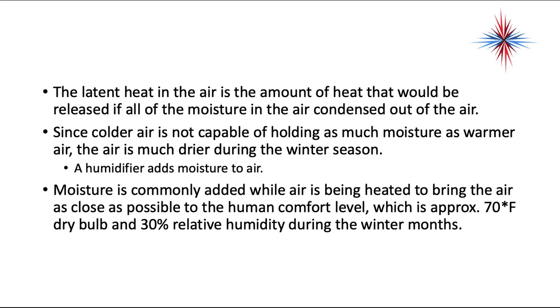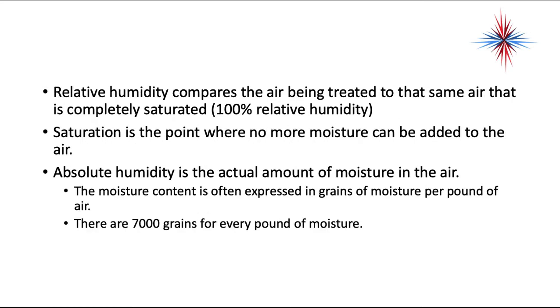Remember, at any temperature, the more humidity in the air, the warmer you feel. The less humidity in the air, the cooler you feel. Relative humidity compares the air that is being treated to the same air that is completely saturated, in other words, wet, with 100% relative humidity. Saturation is the point at which no more moisture can be added to the air without it raining.